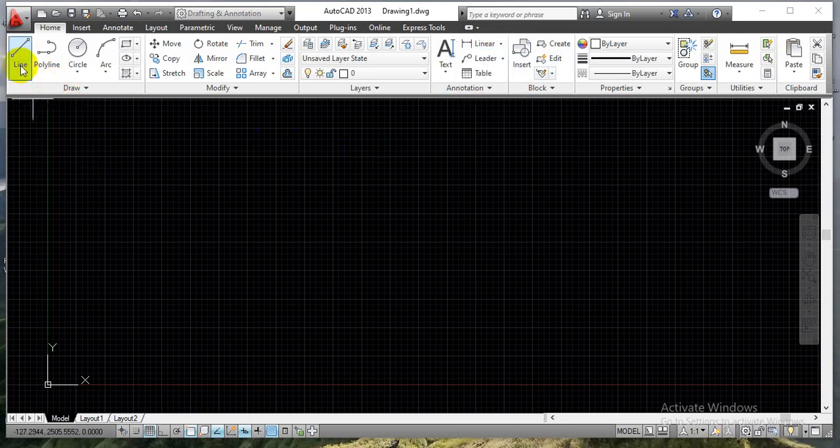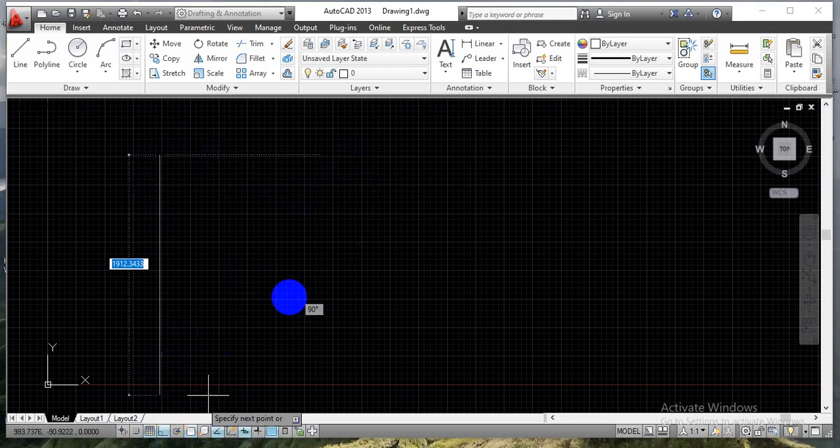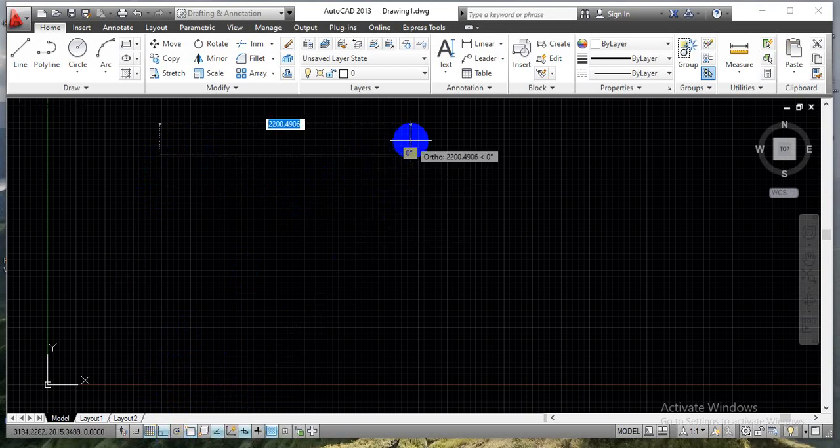Now let me select this line command. I am not going to draw a rectangle for the A3 size. Lately I am going to use any point over this workspace, because we are going to understand how to use these linear dimensions, inclined surfaces, or the jogged dimensions. Let me select any one point over this workspace and click there. Now, to have a proper horizontal line we need to turn on this ortho mode command. Just click on that so that we can have an exactly horizontal line.